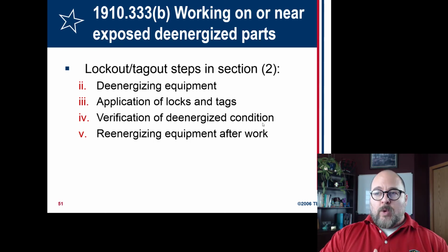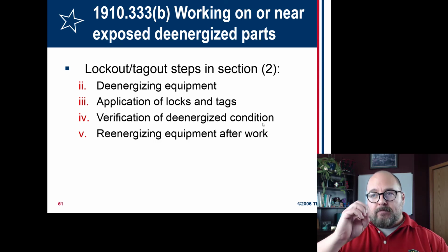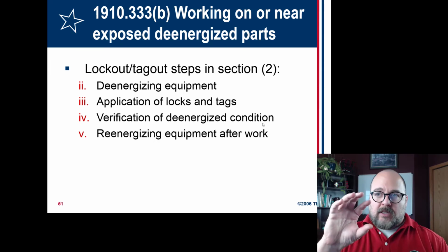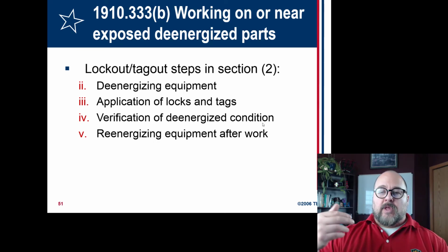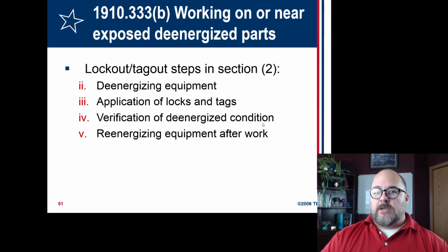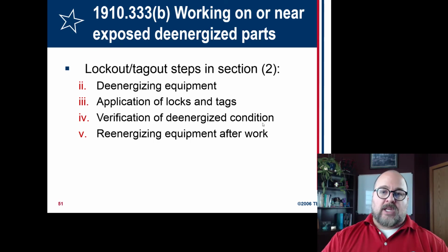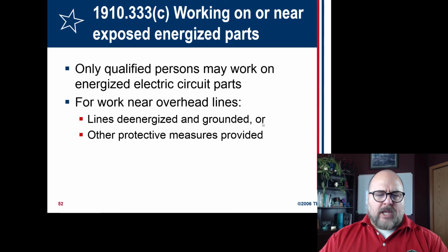And there's a systematic way to go through and turn off a circuit, lock it and put a tag on it so that you're the only person who's able to turn that back on again. Because you put a lock on there, you have the only key. The tag indicates to anybody else who has it. Okay, we'll get into that later, of course.